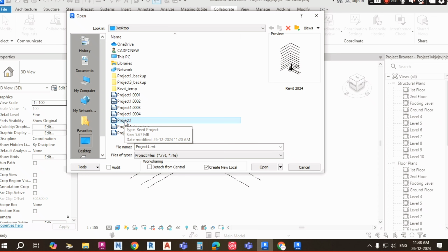So that is the reason, while creating, they also show the dialog box. This is the first time you are going to create a work sharing enable. So whether you want to say yes or not, it is going to show you some warning message. If you proceed, you have to keep proceeding. But you have to do that, because while working in a team, you have to proceed with the central model file only.